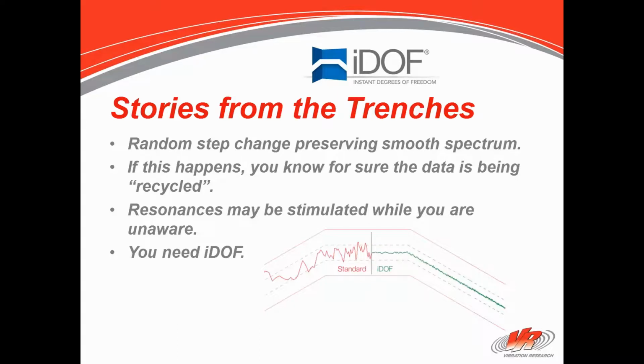If it is, it's in fact dangerous, because whenever you do a level change on a mechanical system, if there's a resonance in it, and that's of course what's going to break things, the resonance will shift. Maybe slightly, maybe a tenth of a hertz, maybe a half a hertz, but it likely will shift. And the problem is, if you use that recycling old data technique to give you smooth lines, you're actually going to be over and under testing at the location of the resonance, and worse, you'll never know it.